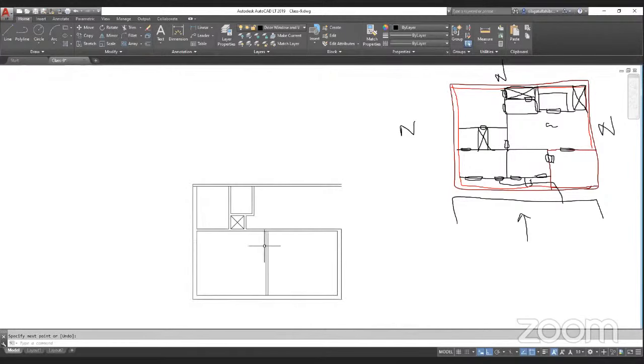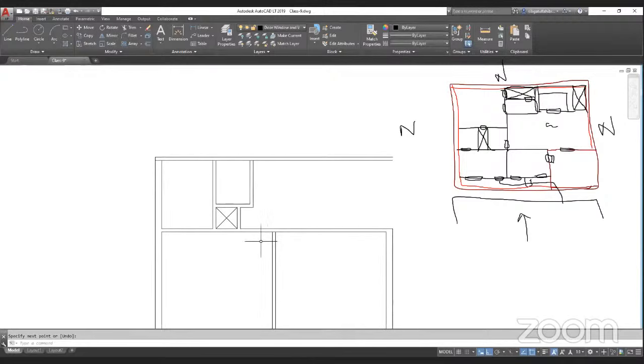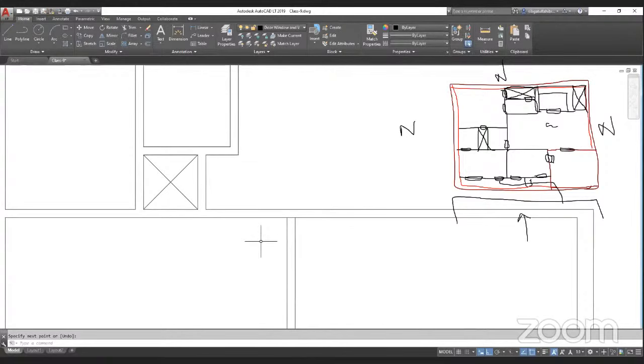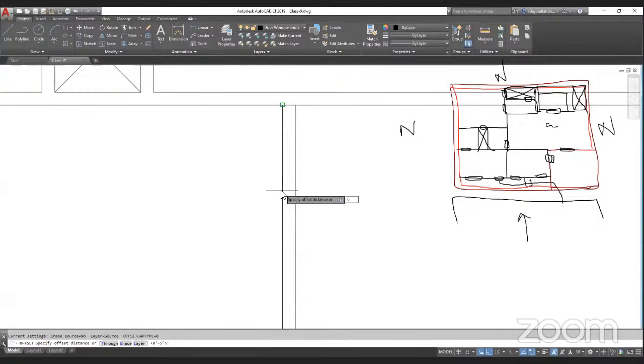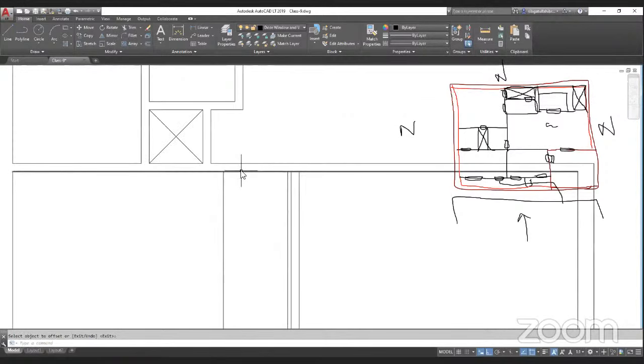All right, then let us make an opening for this bedroom. I'll take the help of this vertical line over here. Let's take a 2 inch offset, then again 3 feet. Then again TR enter. Holding the shift button, I'm going to extend this line and then trim this line. Holding the shift button, extend this line, then releasing the shift button, trim this line, and that's it. So we are done with the opening of one room.